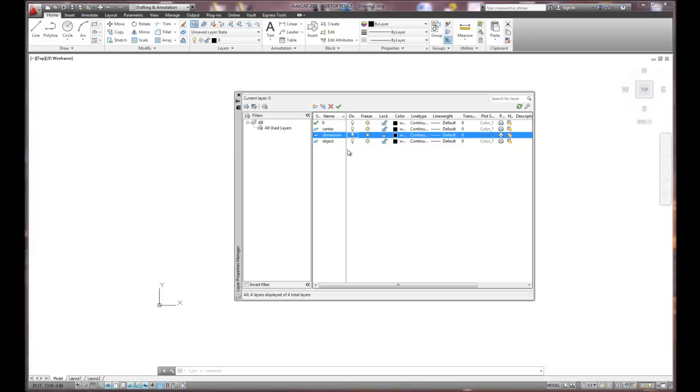A little snowflake will appear if you freeze the layer. It's automatically turned off, meaning even though it might be saying that it's on, when you freeze it, it's automatically not visible. And that ultimately saves computing power because you're telling it not to compute that data. And so that's how we utilized freeze and then the subsequent thaw when we were creating drawings.